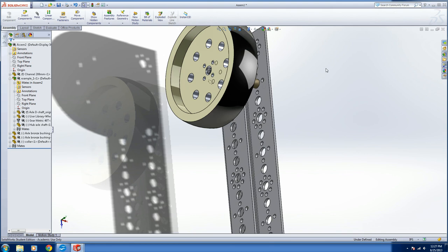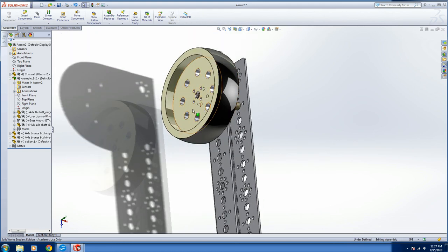So what the lock button does is it fixes a part in the middle of space, and it is not allowed to move anymore. However, if your whole thing is not restricted and you move a part using move component, or you accidentally grab and drag, you will have parts flying all over the place because you A, moved a part, and B, you left everything behind that you have locked.